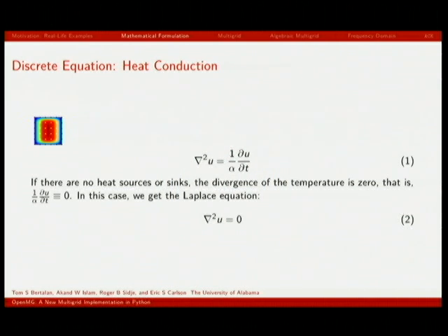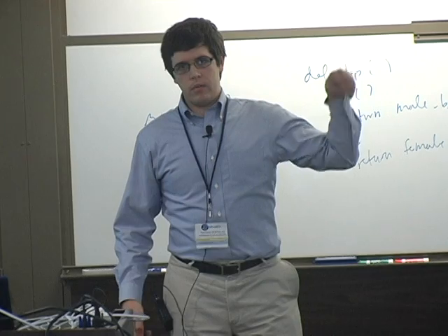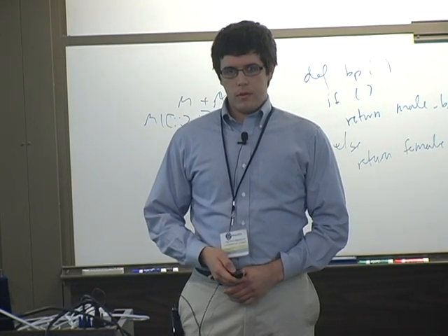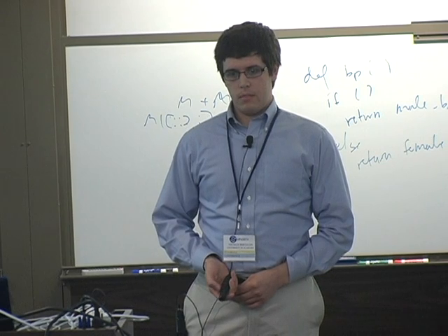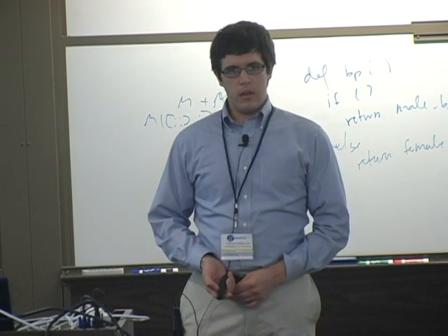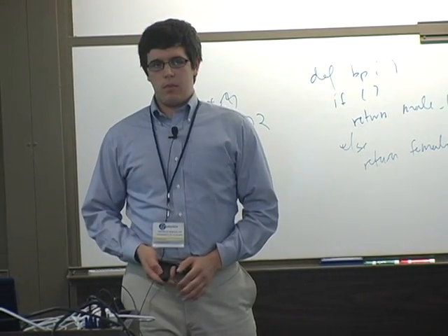Again, the constitutive equation for this example problem uses the Laplacian operator. The right-hand side with the time derivative can be eliminated if inside the object there are no sources of heat generating temperature increase, and no places where heat is being drained away. This is not necessarily true in our porous media problem, where you might have a well injecting CO2 and another well pulling out oil. But if you set that to 0, then you have this simpler equation, the Laplace equation. It's a very simple equation, good for a model problem to solve.